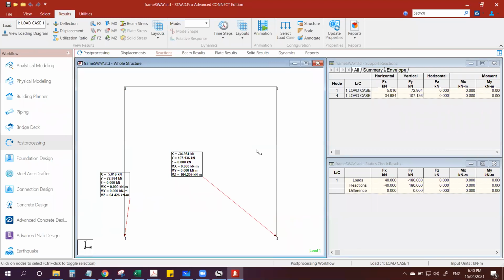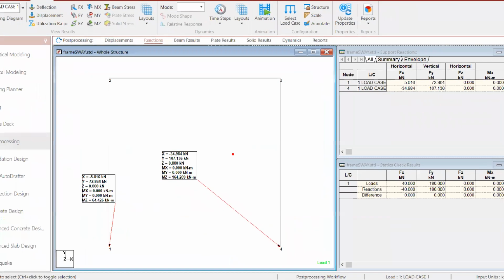Okay. And this is further justified because remember, in our code, for concrete, we maintain a strong column, weak beam. That means your column will be much greater than the beam, so it could carry that much axial force. So we ensure that the column is stronger, such that axial deformation, especially in a typical low-rise building, will not be that much. Okay? And this is our assumption in this approximate analysis of a building frame.